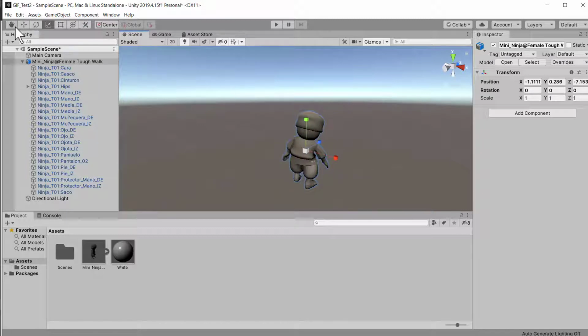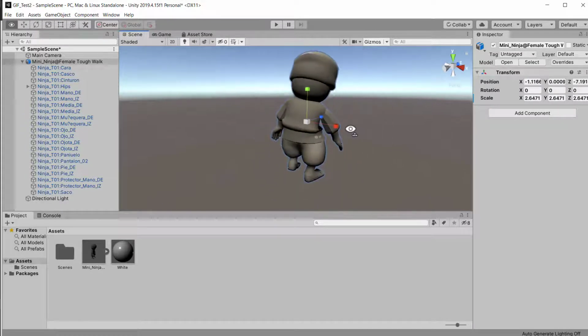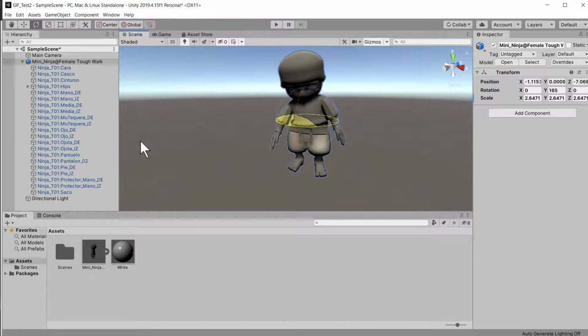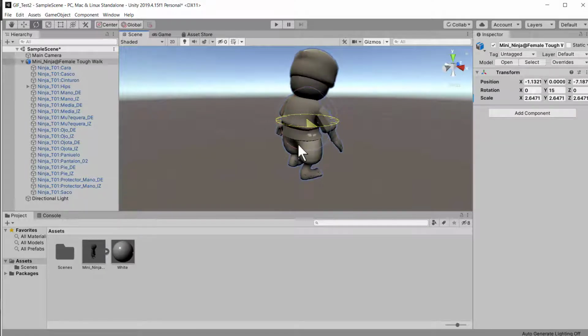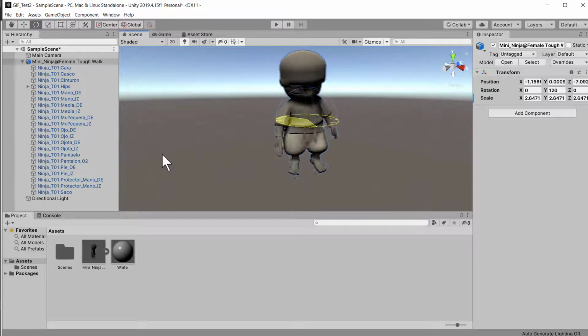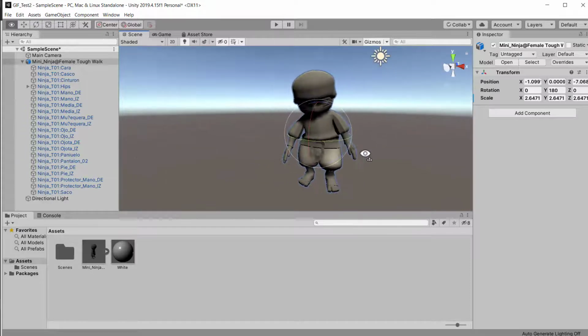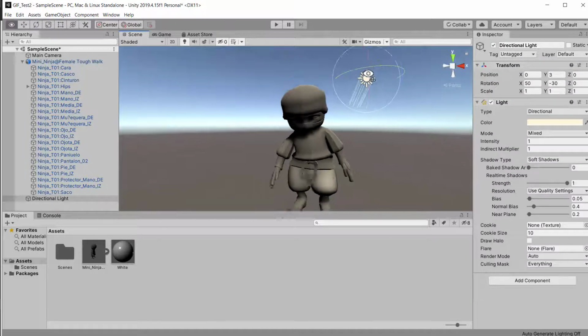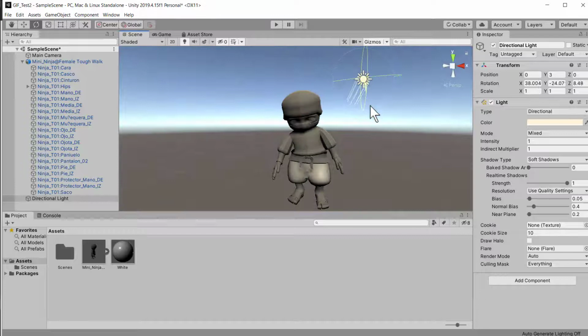We'll scroll through these options here. So Q, W, E, R, and T for scale, so you can scale them up. And if you hold Control while you spin, you'll get nice even numbers, 5 degrees at a time, or 15 degrees at a time rather. You can make a nice easy 180, and we're going to take the skylight and just brighten him up a bit.